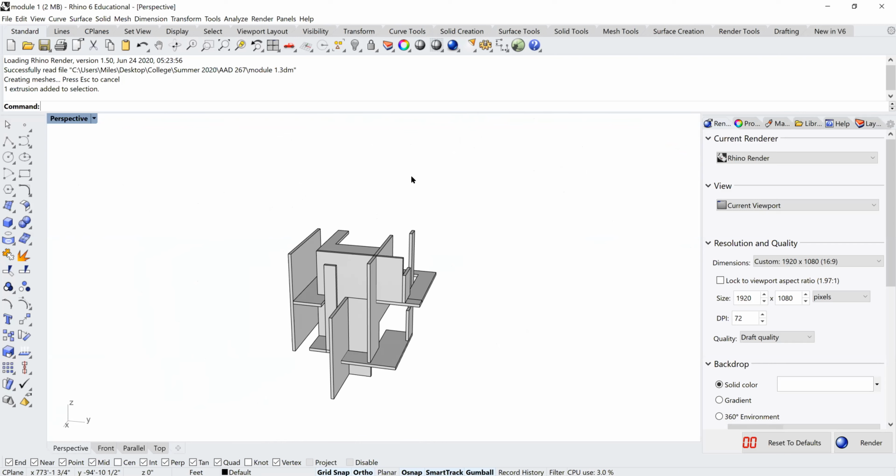But in this situation here, actually bring this down past the slab so that instead of sitting on top, the wall actually extends down past it like this. That'll help you, because then you'll put reveals on this thing, right? And then you'll have the floor back beyond it, and so you can sort of get rid of that. So you might consider applying these things just like this. That kind of detail will work better than this detail where you have the wall sitting on top of the floor. Right. Can you explain that one more time?